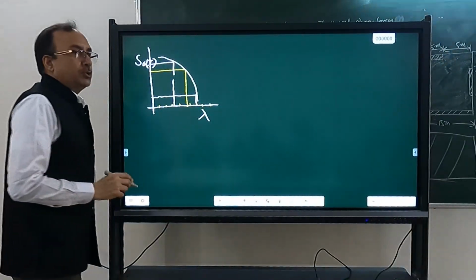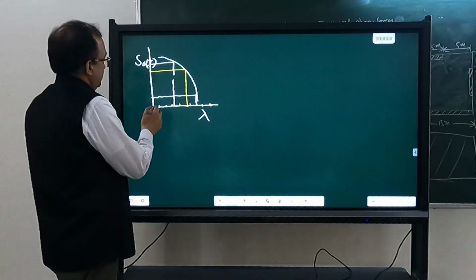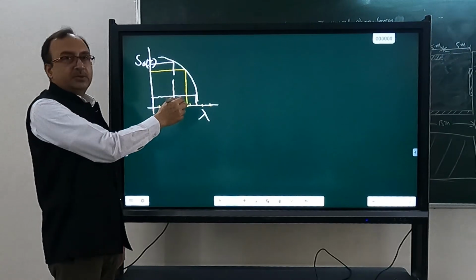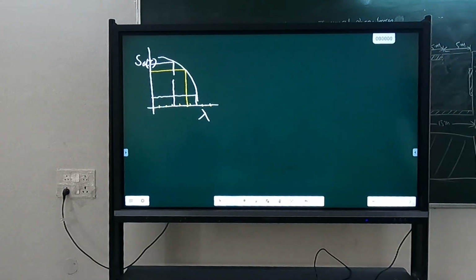So if it is 2% in 50 years, how much will it be in 1 year? Roughly, you will obtain it using that formula which I have given between return period and this. What is the probability in 1 year if we assume that it is occurring uniformly? 2 by 50, percent. So like that you can give 0.0001, or 1 into 10 to the minus 4, 2 into 10 to the minus 4, 3 into 10 to the minus 4. So like that, you will assign the probability of occurrence. Generally, it is the annual rate of occurrence. Any other question?